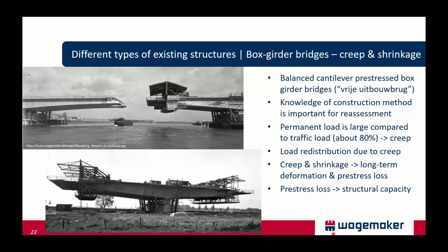And this is also done from the other side of the river until they almost meet. And then closing segments are placed here in the mid span that you see in the top image, and also near the land connections, and then a continuous structure exists.